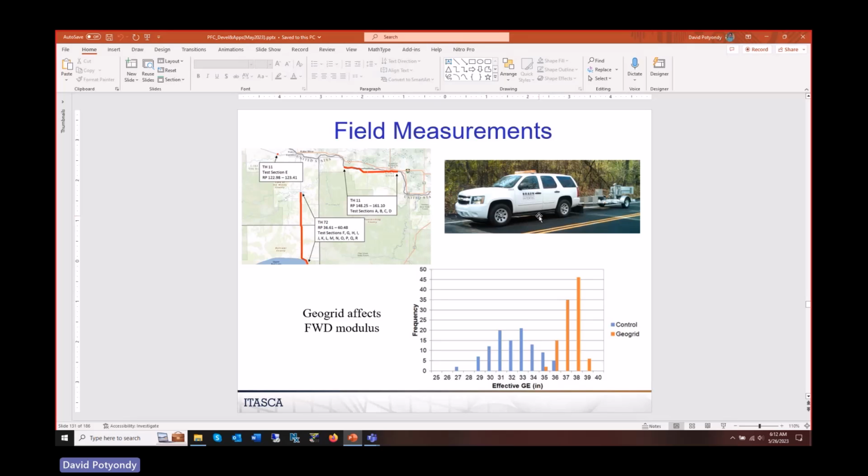If you were on the end of a dinner table, and I was on the first end and I got excited and I pounded the table, your silverware would shake, right? So the same thing happens with the roadway. Based on those measurements, they're able to back calculate the stiffness of the system. So they do this, it's a non-destructive test.